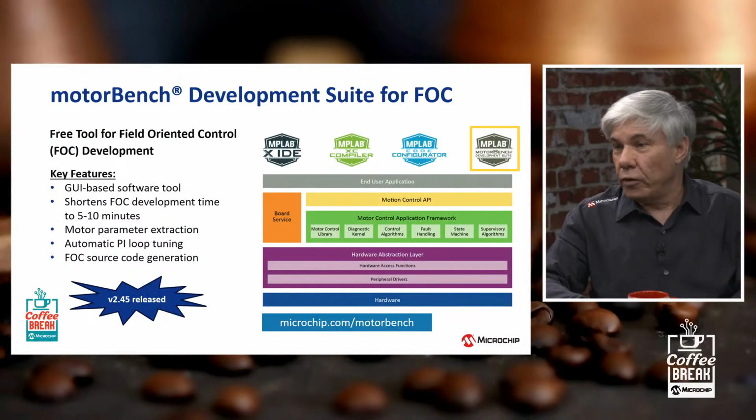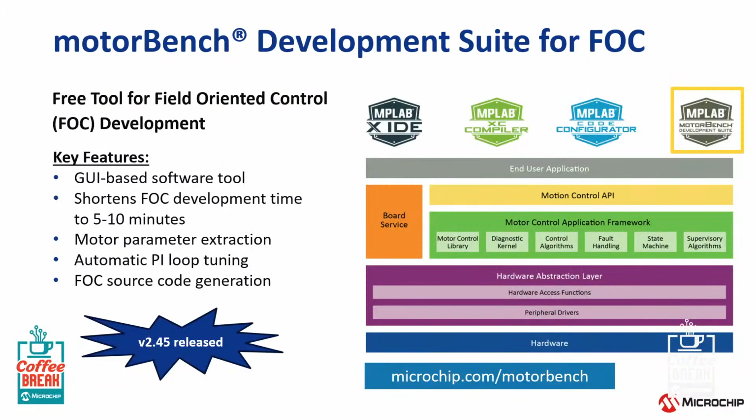So fortunately, we have a free tool called MotorBench, which is a GUI, and it runs on your PC, and it's part of the MPLAB X IDE. And it does 3 things. It will extract the motor parameters that we need in order to run field-oriented control. It will tune the 3 PI control loops for speed, ID, and IQ. That is what makes the basis for field-oriented control.